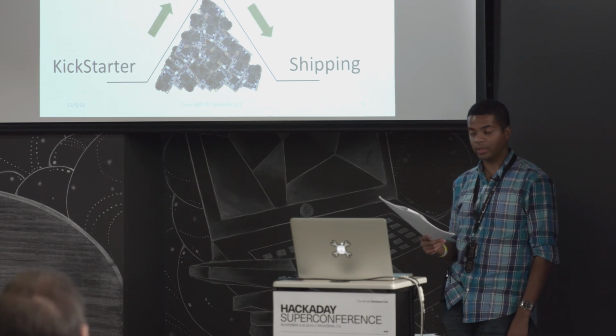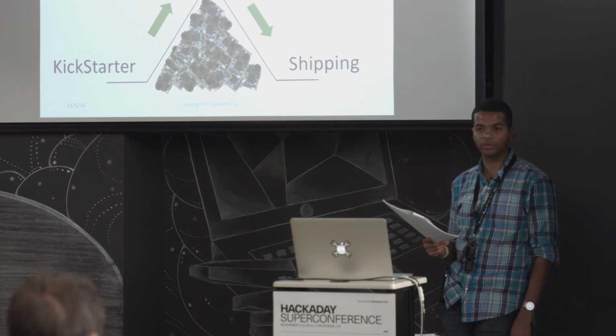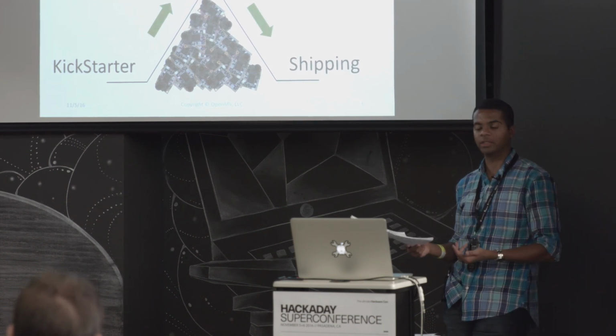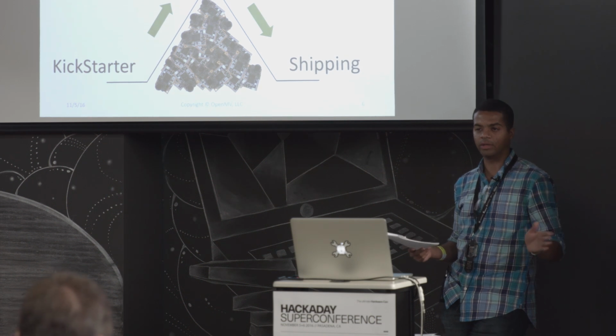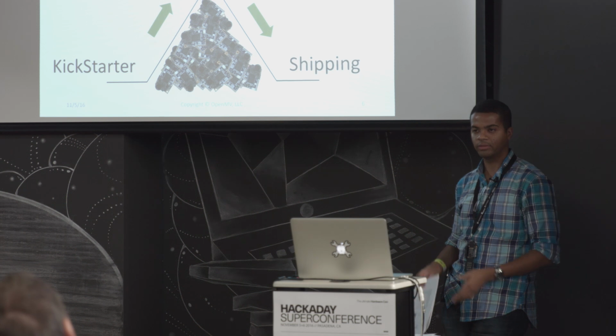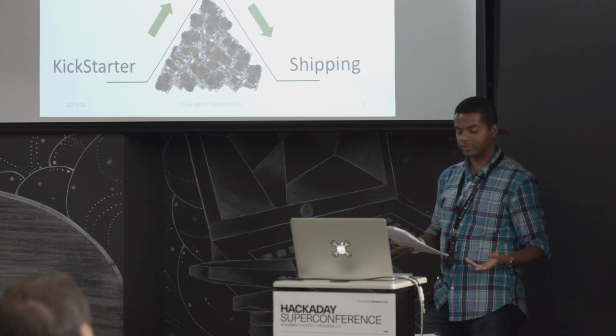It had built-in JPEG compression, which allowed us to take high-resolution pictures and store them on the microcontroller's RAM. Having JPEG compression meant it would literally just send you a JPEG image byte for byte on an 8-bit data bus, and you would just store it in memory, write that to disk, and you were done. It was also cheap, costing $2 a piece.